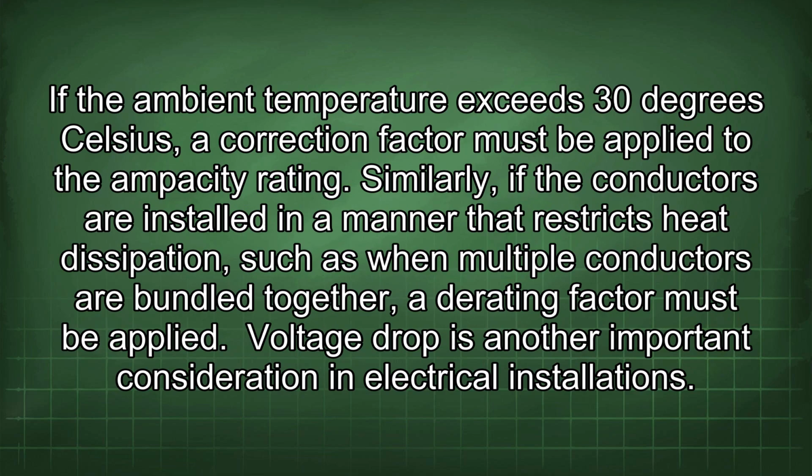If the ambient temperature exceeds 30 degrees Celsius, a correction factor must be applied to the ampacity rating. Similarly, if the conductors are installed in a manner that restricts heat dissipation, such as when multiple conductors are bundled together, a derating factor must be applied.